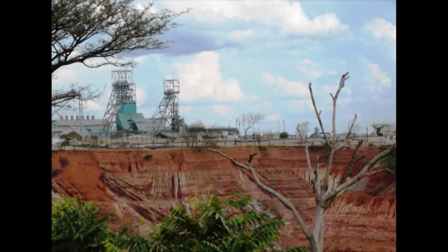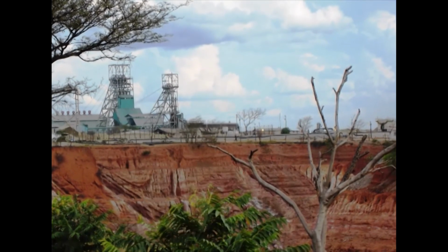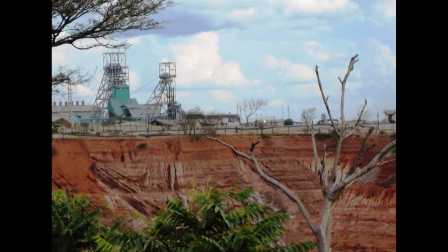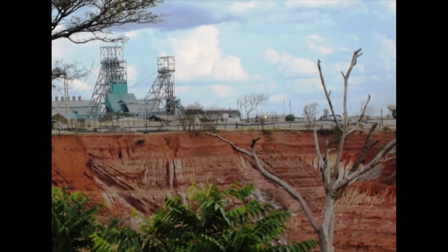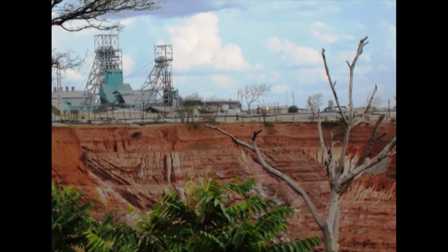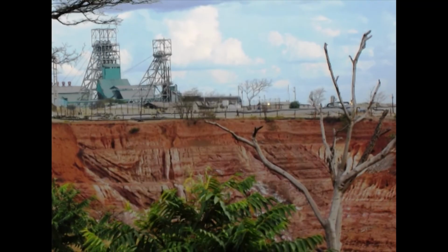Blasting breaks a cone-shaped opening in the rock mass around the hole and allows the blasted material to remain in the stope during the production phase so that the rock fill can assist in supporting the stope walls.